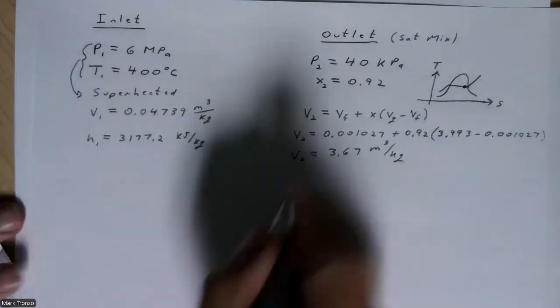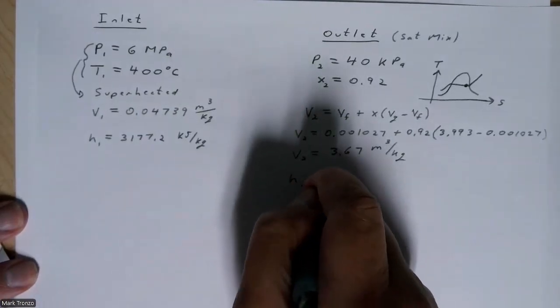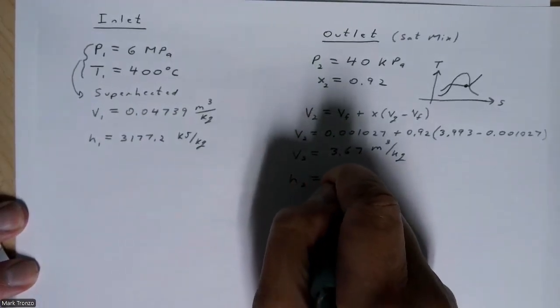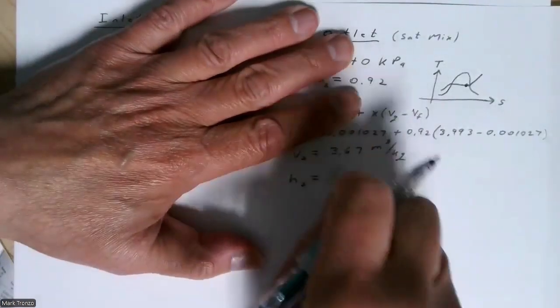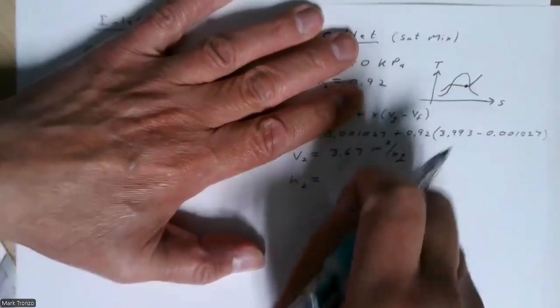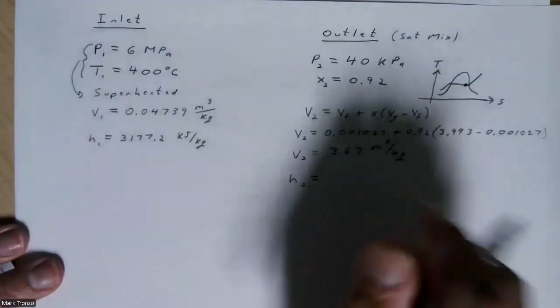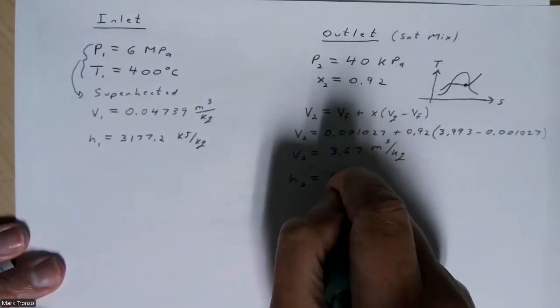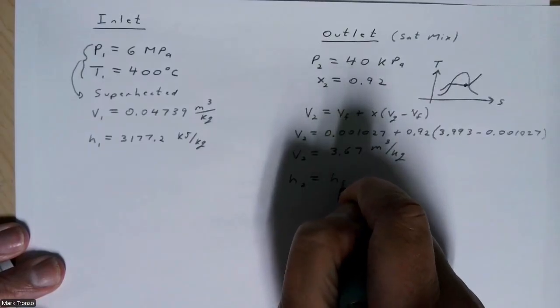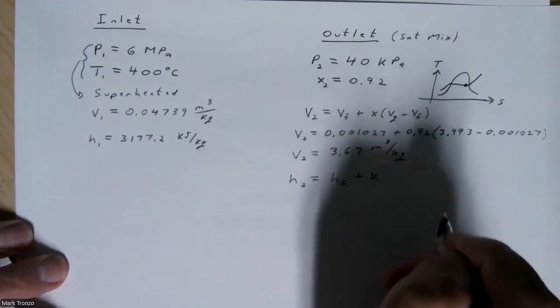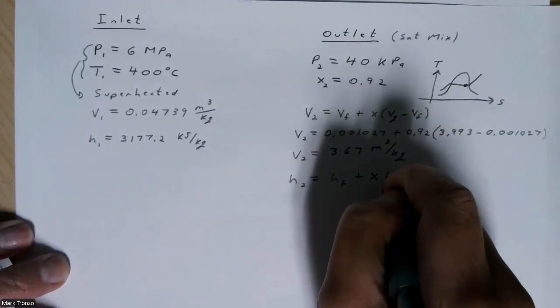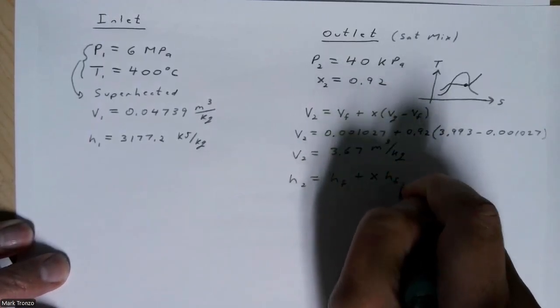So let's do the same thing for H2. Now for H2, for the enthalpy, we don't have to actually do the subtraction up here because at least my table has that done for us. So I can just use this HFG.